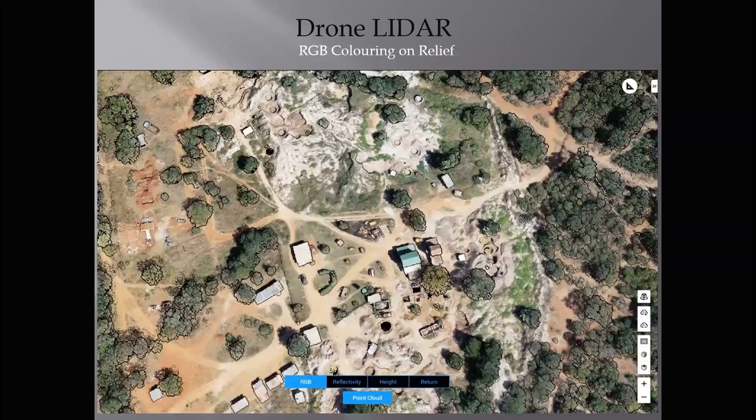What about the cameras, the LiDAR, the altimeters, the hyperspectral, all of that? Okay, here's an example of what we do with LiDAR on a drone. LiDAR are usually quite expensive. If you do it with an aircraft, much cheaper with a drone. What we can do is we now measure with the laser. LiDAR is laser interferometry, basically. This laser fires, again, something like 20,000 times a second, and it picks up every little blip in the terrain. So here we're doing a digital terrain model, essentially, but it can fire through leaves because it fires so often. Goes right through the leaves of the trees and everything, maps the ground.